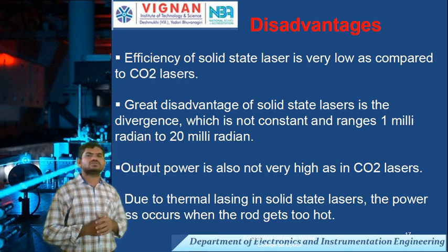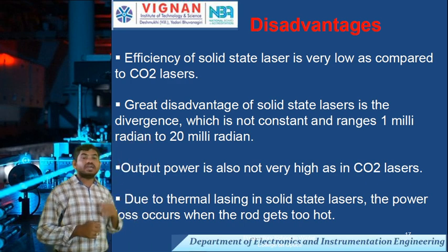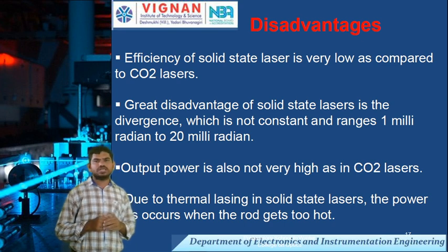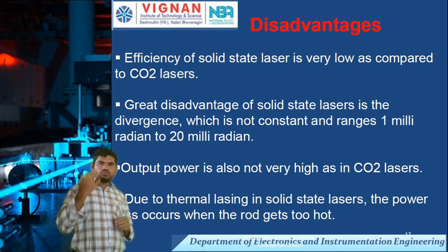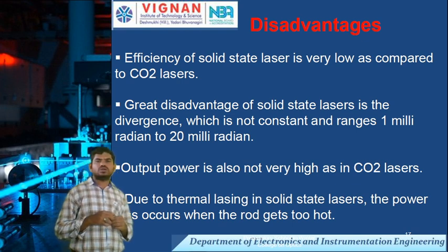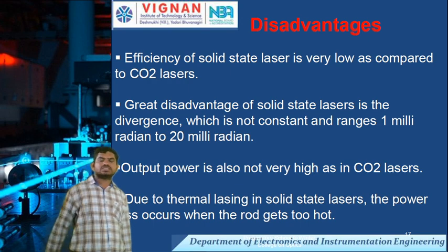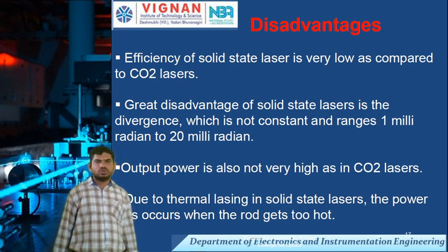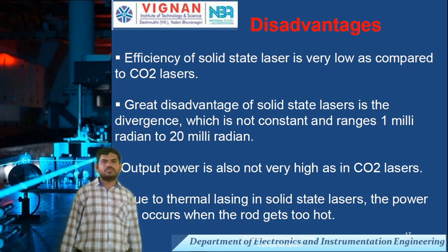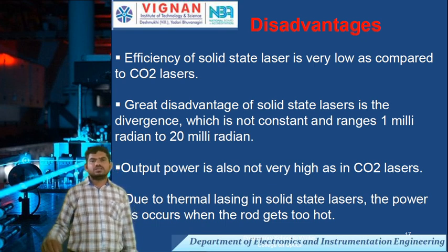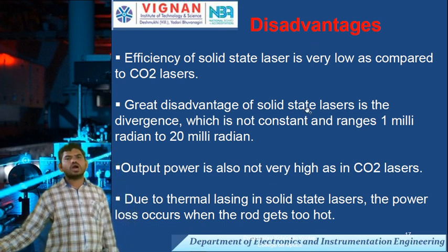A great disadvantage of solid state lasers is the divergence, which is not constant and ranges from 1 milliradian to 20 milliradians, and the output power is not as much as the carbon dioxide laser. Due to thermal loss in solid state lasers, power loss occurs when the rod gets too hot.